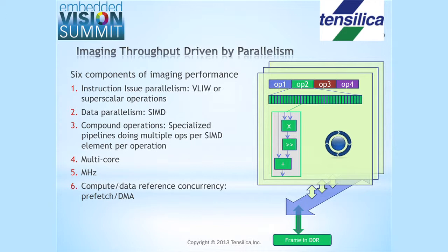You are going to see compound operations where you build a pipeline that doesn't do just a simple RISC operation, an add, a shift, a multiply, but does a sequence of those things. A multiply, a normalization, an add, maybe some saturation. And those compounding of operations are the things that are most imaging specific, because they typically reflect the imaging data types and the typical patterns of operations that you will find together within an imaging application.